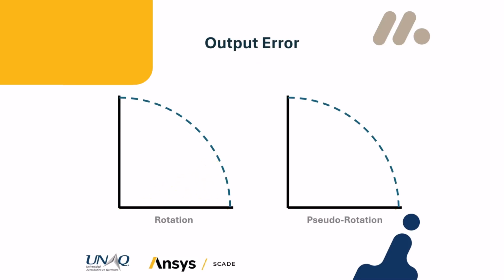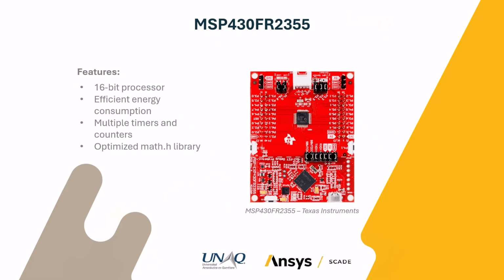The disadvantage of CORDIC is that the operations made by the algorithm are approximations, so there will always be an error whose magnitude depends on the number of iterations made. This error is due to the fact that real rotations are not performed. The algorithm performs pseudo-rotations where the vector components move by a fraction of the previous iteration's vector length.